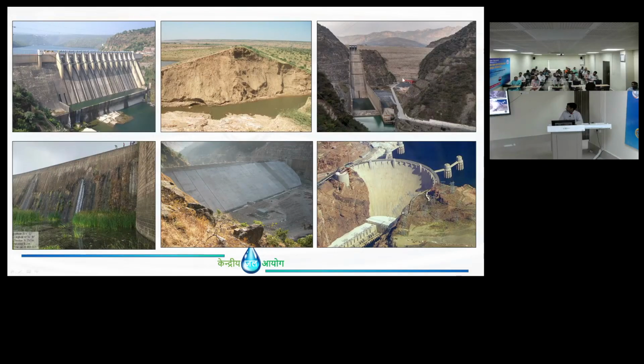So this is a rock-fill clay covered dam, and a further upgradation to these dams is to minimize the section. You can see the slope is almost 3 horizontal to 1 vertical. To reduce the material quantity, we can have a concrete face on the upstream side. That is called a concrete face rockfill dam. I will explain that in detail in the coming slides.